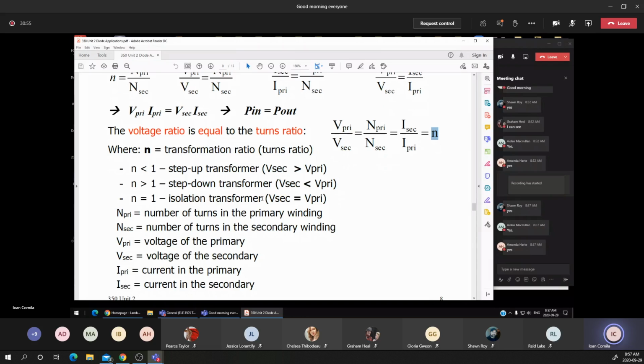If you remember, we used an isolation transformer and an auto transformer on the same equipment. But most of the time, you will see an isolation type transformer used as a safety device in different applications. For example, I use an isolation transformer in the labs to prevent any electrical shocks for the students when they are touching those AC voltages.